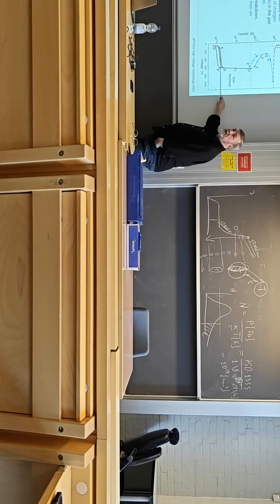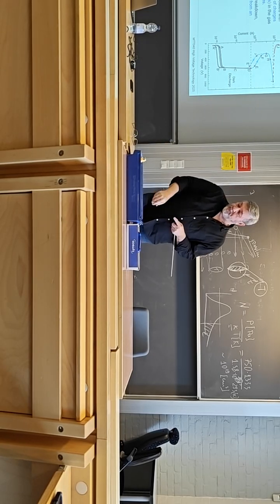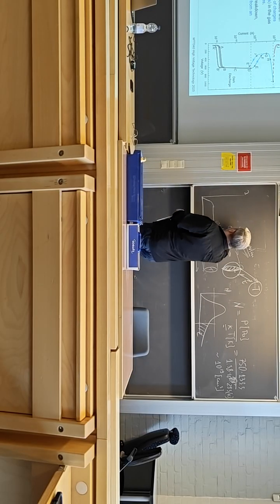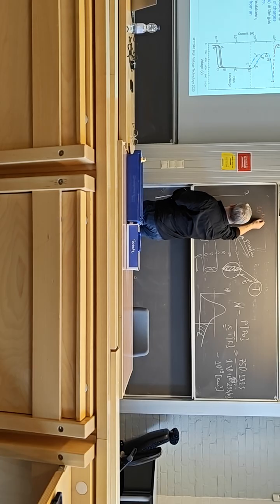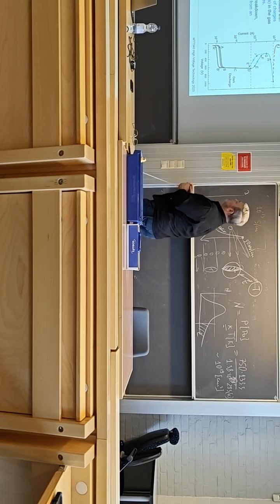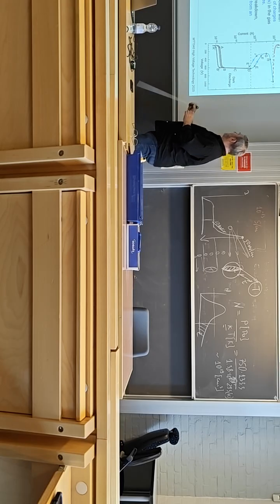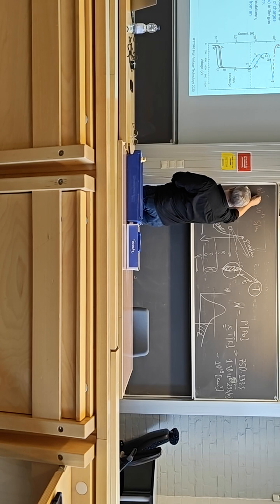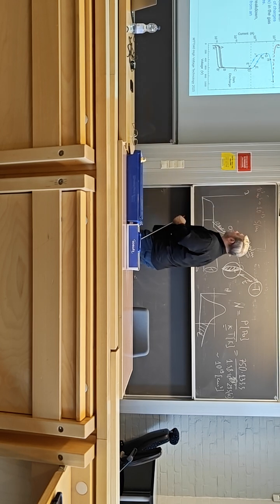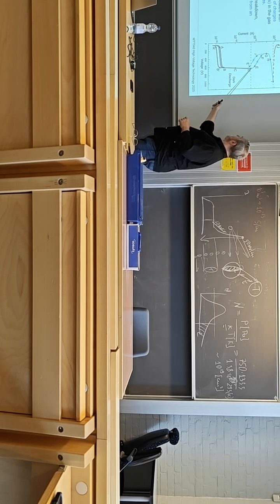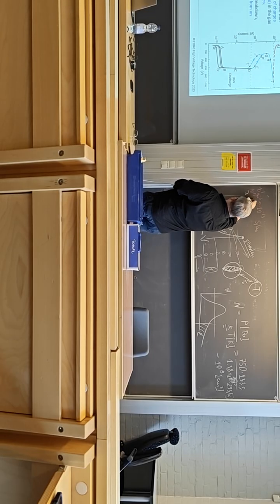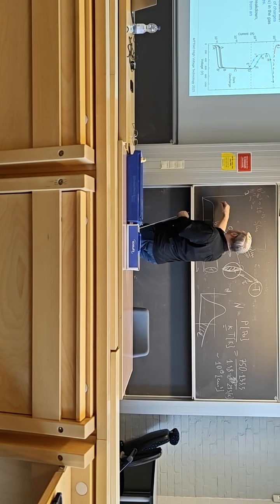So here, you remember we calculated the conductivity like 10 to minus 13 Siemens per centimeter, just because of the low number of charges, which was like 10 to 3 per cubic centimeter, right? But here, we typically have at breakdown something like 10 to 13 at least electrons per cubic centimeter.